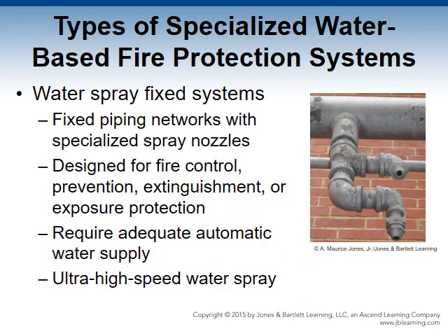Water spray fixed systems. These are fixed piping networks with specialized spraying nozzles. They are designed to protect a specific piece of equipment or the structural member surrounding or supporting the equipment. They may also be designed to function in conjunction with other fire protection systems as part of an overall fire protection installation plan. They are designed for the purpose of fire control, prevention, extinguishment, or exposure protection.